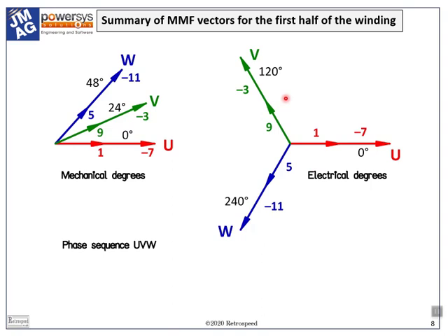But these vector diagrams are not phasor diagrams. They are space vectors, frozen at particular instants of time. In all cases, the same value of current is implied because the magnitudes are the same.